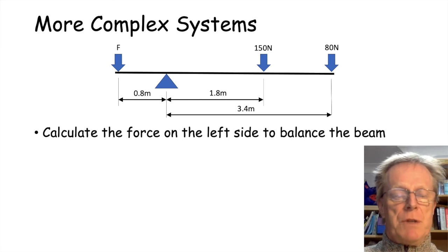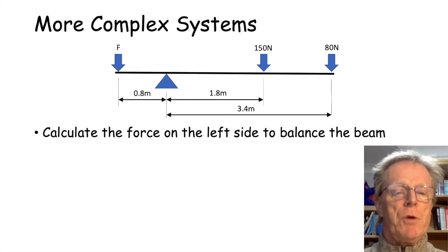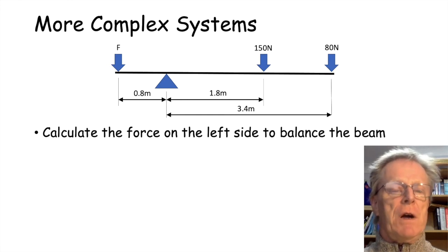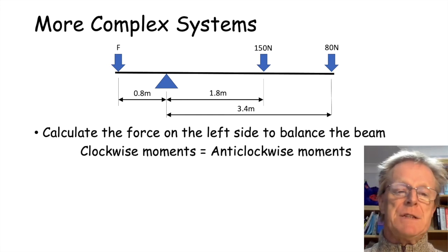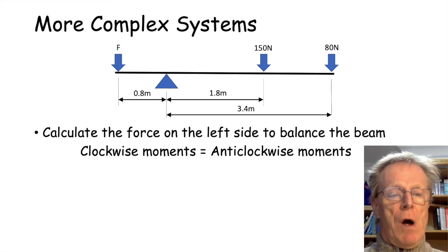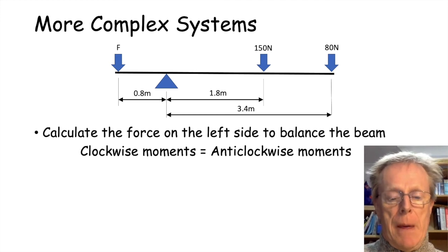We state the principle of moments. Clockwise moments equals anti-clockwise moments. And I generally find for these types of problems, it's best to work from one side to the other. So from left to right. So look at each load and work out which way it's going to go and then put it into the appropriate side of the equation.